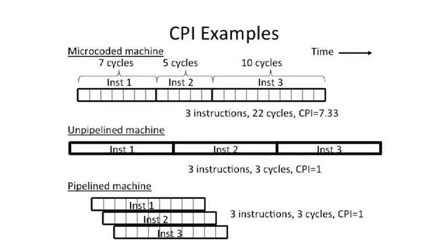And in an ideal pipelined machine, we'll actually have multiple instructions executing at the same time. So time goes left to right on this graph. And we'll be able to cut the instructions. And in an ideal world, we'll have a CPI of 1. And our clock period will also be short. And you can see this is sort of smaller than those other solutions. And this is why we start to think about pipelining. But we're using transistors to do this.